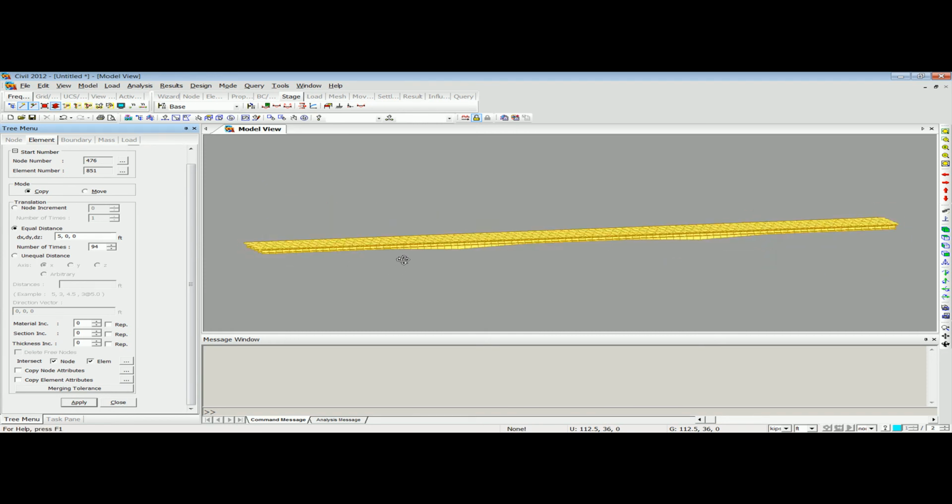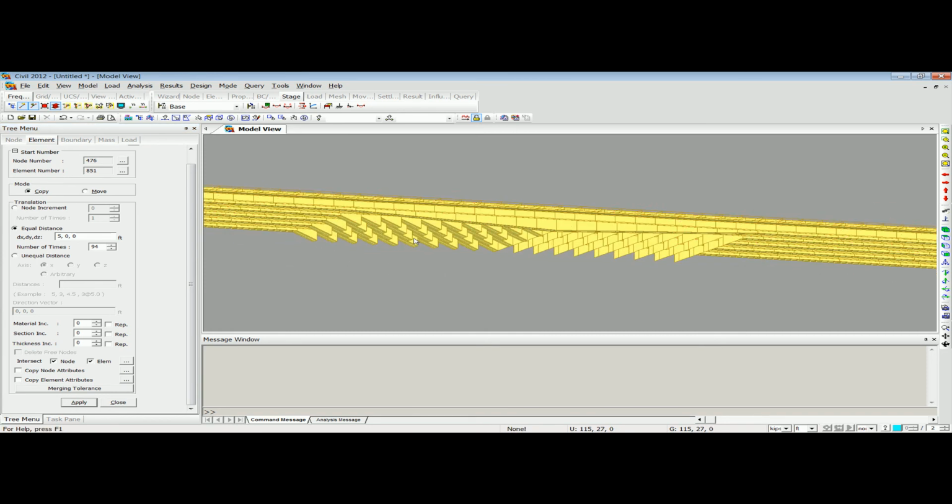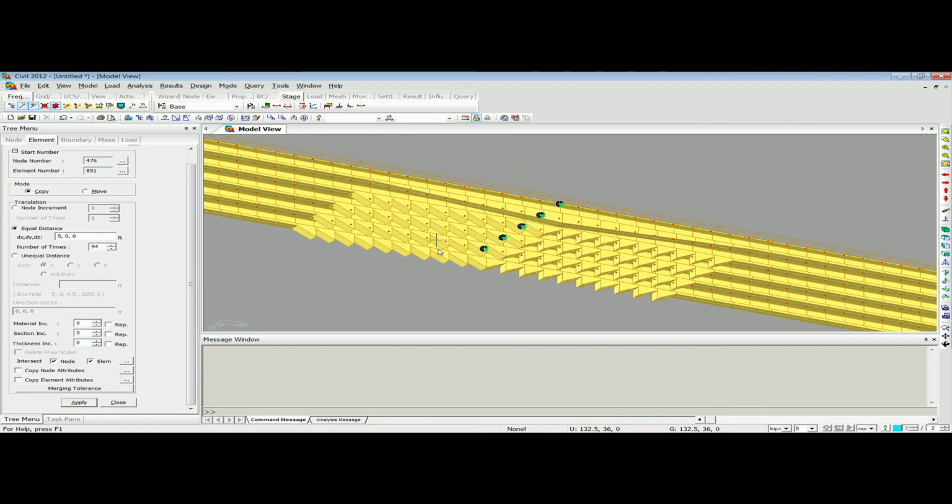Okay. One thing that I want to point out is that you can see that the perfect tapering doesn't appear in the other girders. For that, you need to select individual girders and define the tapered section group for the elements on which you want to make the tapered section.